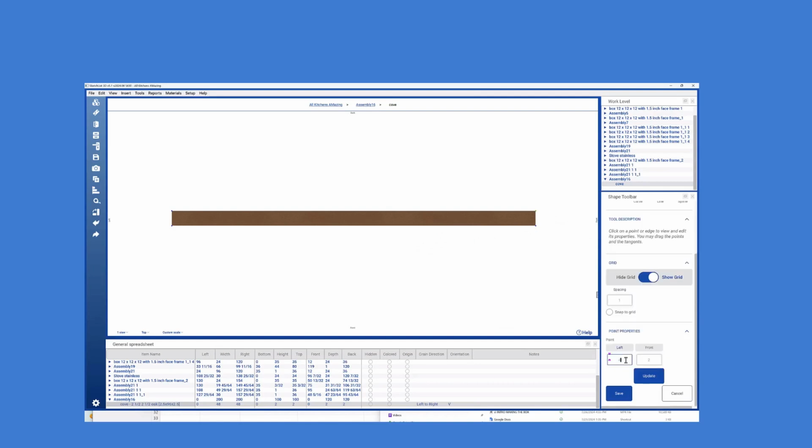Go to the grid and set the left value to 46. That is 48 inches with -2 for board thickness. Click the top left dot and change its value to 2. You will see 45-degree cuts on both ends of the board.